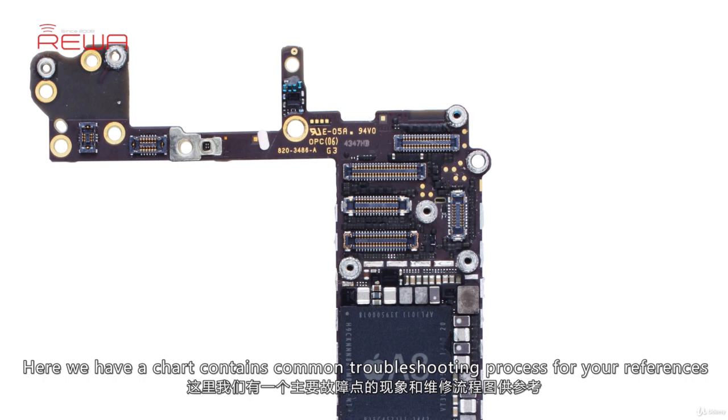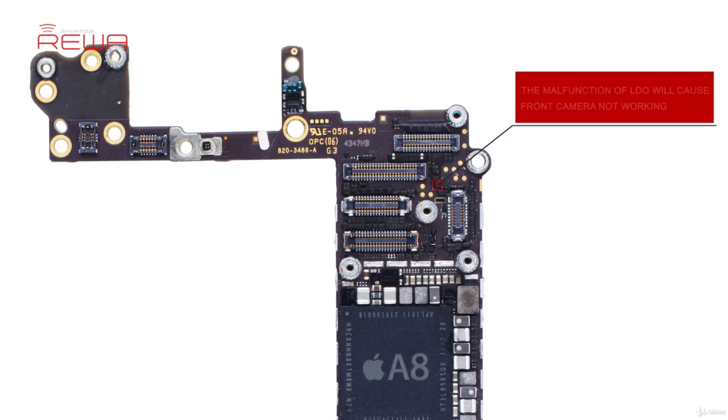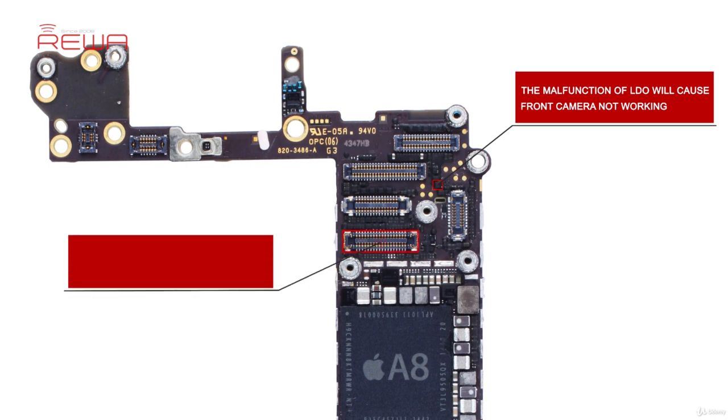Here we have a chart containing the common troubleshooting process for your reference. Common fault points on the front camera module. The malfunction of the LDO will cause the front camera not to work. The malfunction of J1111 will cause the front camera not to work.